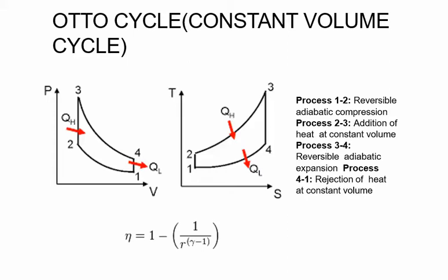The isentropic process of compression or expansion implies that there will be no inefficiency and no transfer of heat into or out of the system during that process. The cylinder and the piston are assumed to be impermeable to heat during that time.